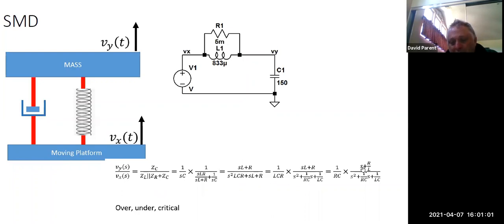And what kind of filter is that? We've seen filters that might have S squared in the numerator. We might have a constant in the numerator. We might have a constant times S in the numerator, for band. And we might have S squared plus a constant, which would give us a notch. But now we have S plus a constant, not S squared plus a constant. And so it's not really a named filter per se, but this will at high frequencies go to 0.